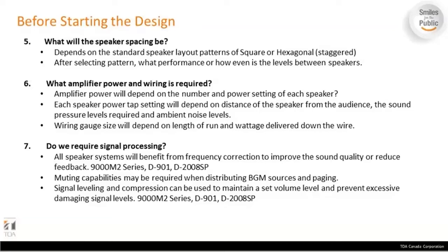Like if it's a warehouse, right, you have, let's say, 30 horn speakers. So your head end is in one unit. When I say head end, your amplifier, your processor, your keypad, all of that is in one place. And the farthest point of your horn speaker will be, let's say, 450 feet. So you have to make sure you use a very thick speaker gauge, pure copper speaker gauge, roughly around 12 to 14 gauge speaker cables, so that you avoid the losses, right?